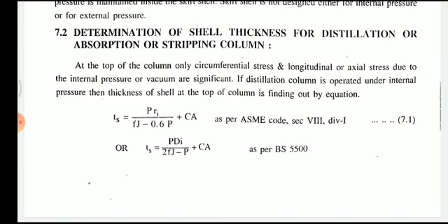Now, the determination of shell thickness for distillation or absorption or stripping column. At the top of the column, only circumferential stress and longitudinal stress or axial stress due to the internal pressure or vacuum are significant.